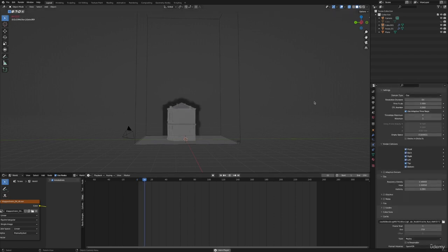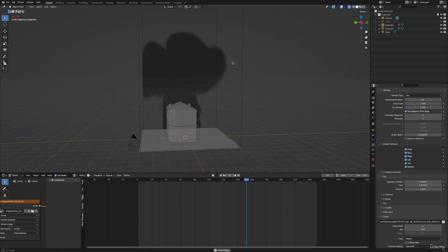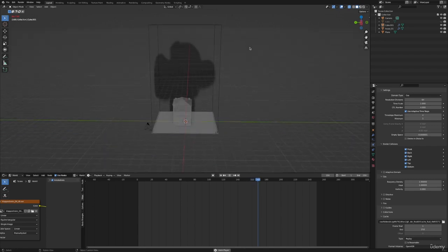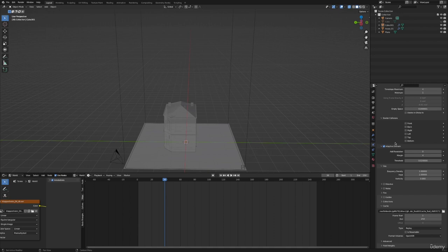Border collisions are not activated here by default, but we can activate them and then you can already imagine that it collides on the left, right, top, and bottom sides, and somewhere else within our domain or with the edges of our domain, behaving accordingly. Now, if you have the border collisions off, there is no collision, and that means that the particles that go outside of our domain are simply deleted.